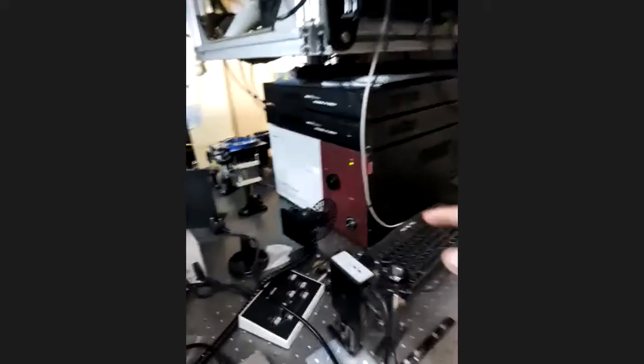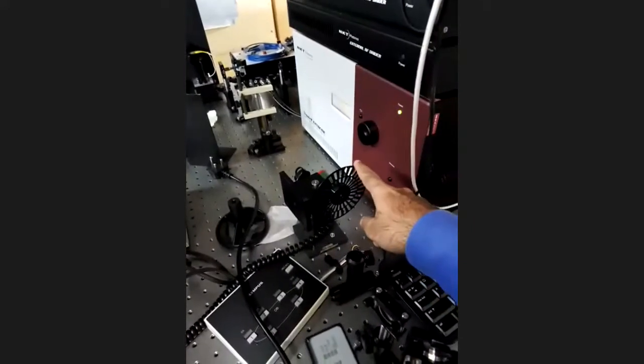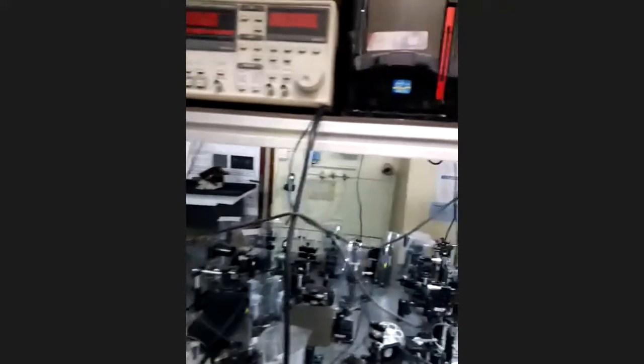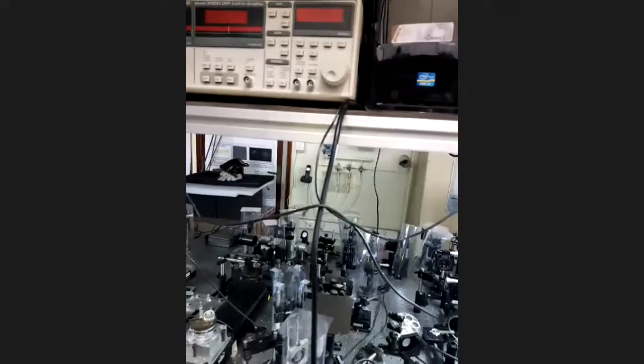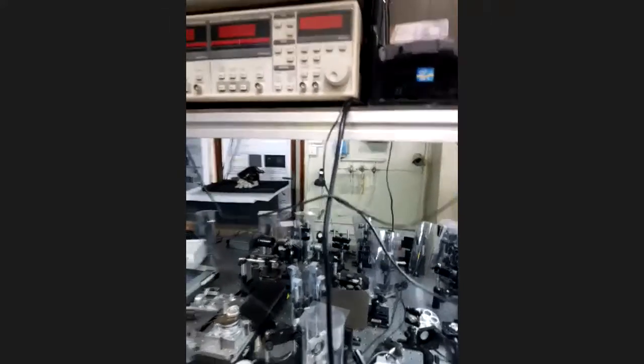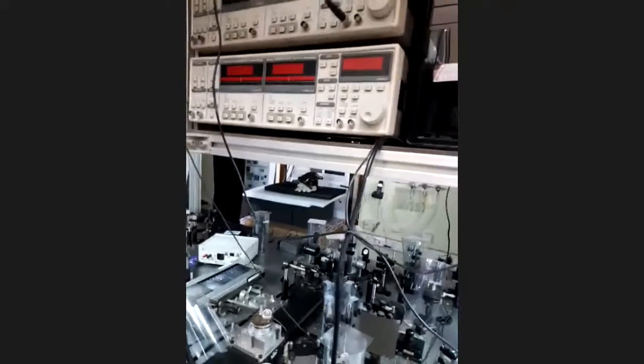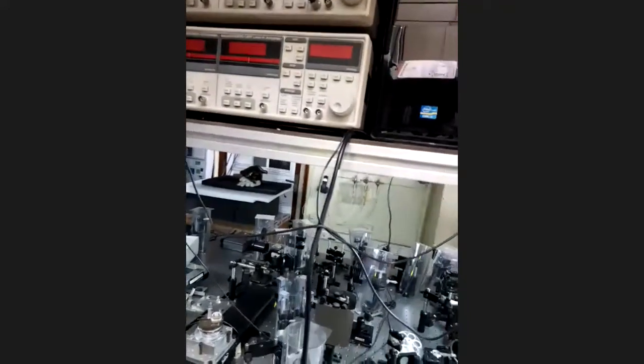So I want to reduce all that. So I modulate my light which is falling on the sample at a particular frequency at which this wheel is turning. And with that reference frequency, I know that my signal is coming only at the frequency at which the light is incident on the sample. So I measure using a lock-in amplifier the signal at that particular frequency to reduce the noise.